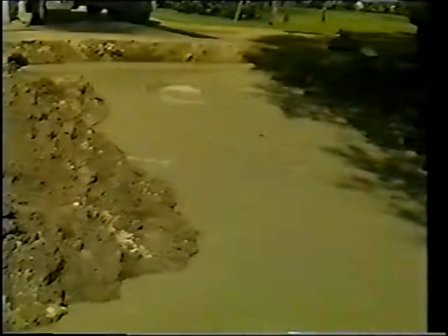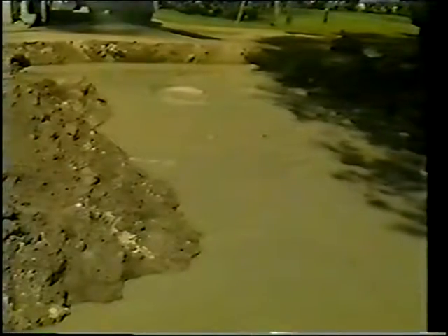Once hardened, flowable fill provides structural support to the pipe, or in narrow trenches, transfers the load to the trench walls. It can be placed up to the top of the trench. Unlike poorly compacted soil, the hardened material will not settle. Flowable fill can have advantages in urban or residential areas where installation and repairs must be done quickly and suitable backfill could be a problem.